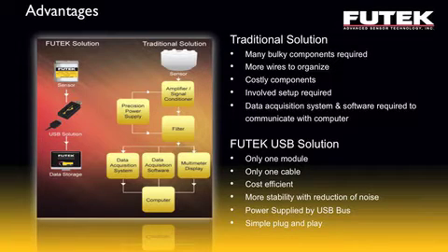In a traditional sensor solution, there may be several components that are required. Some of those could be an analog amplifier or signal conditioner, as well as a precision power supply. It may also require some type of filtering. You would also be using a data acquisition system or data acquisition software for data capture, or also a multimeter or display to view the data. And finally, all these instruments would be connected to a PC.